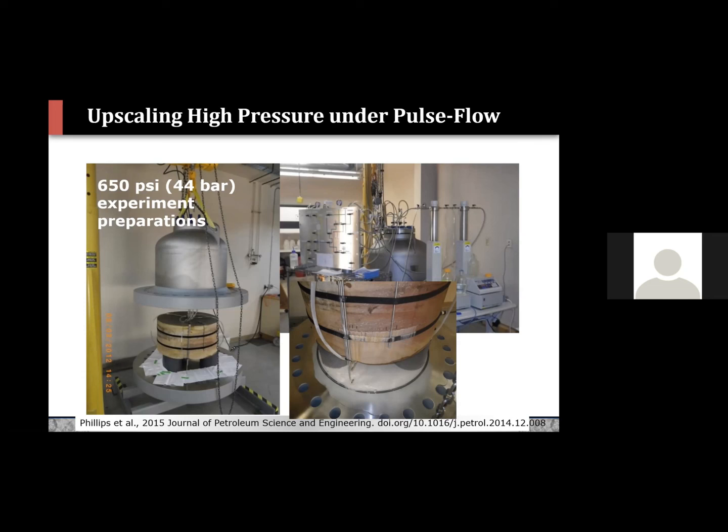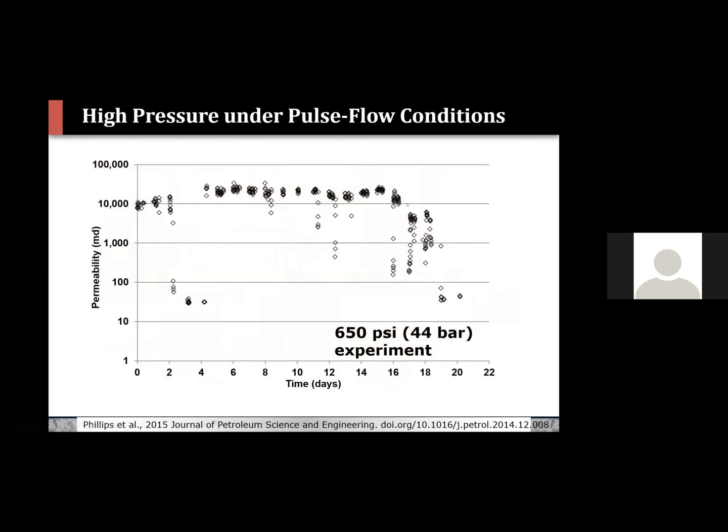And we were able to see, again, it worked very effectively. Here on the picture, you can see a carbonate crystal forming at the edge of this. This has been fractured, and we can actually see carbonate crystal plugging of this fracture zone in this Berea sandstone. So it seemed to effectively work. And again, we were able to show very significant decreases in permeability. Again, 3 orders of magnitude decrease in permeability through this pulse flow injection strategy.